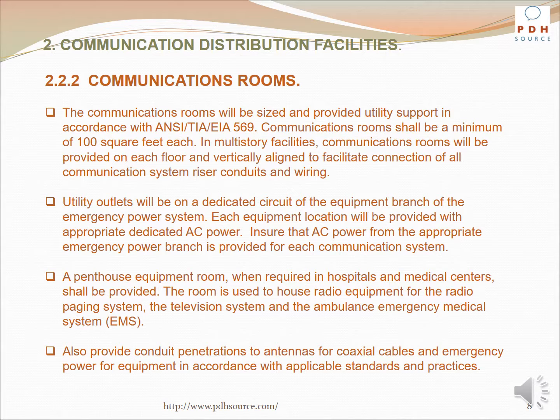A penthouse equipment room, when required in hospitals and medical centers, shall be provided. The room is used to house radio equipment for the radio paging system, the television system, and the ambulance emergency medical system. Also, provide conduit penetrations to antennas for coaxial cables and emergency power for equipment in accordance with applicable standards and practices.